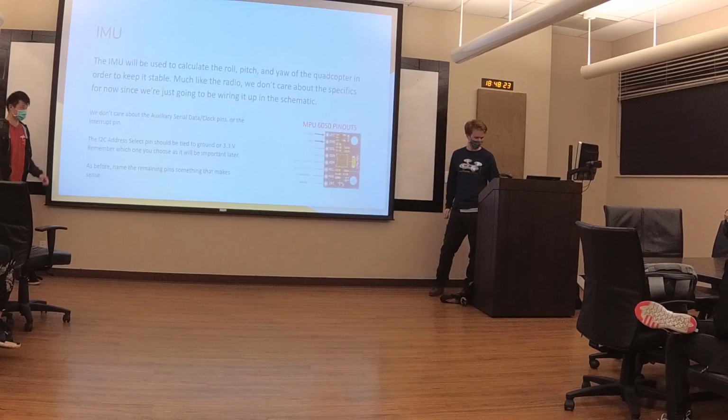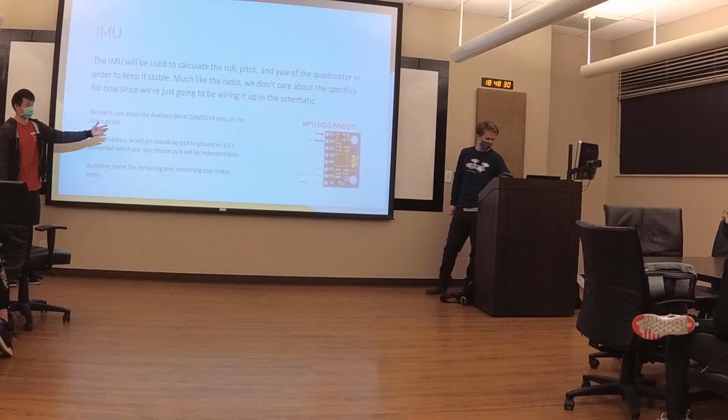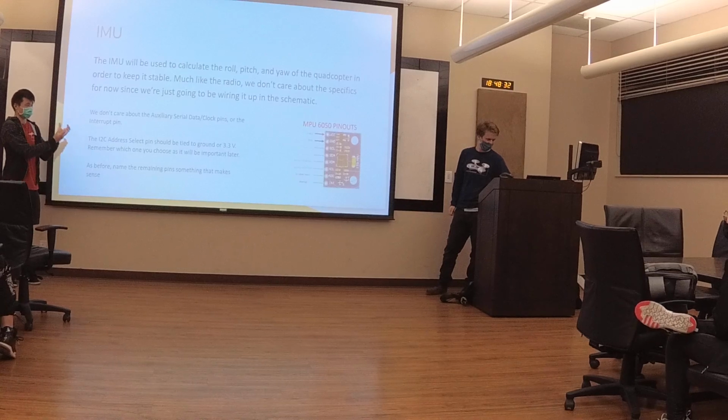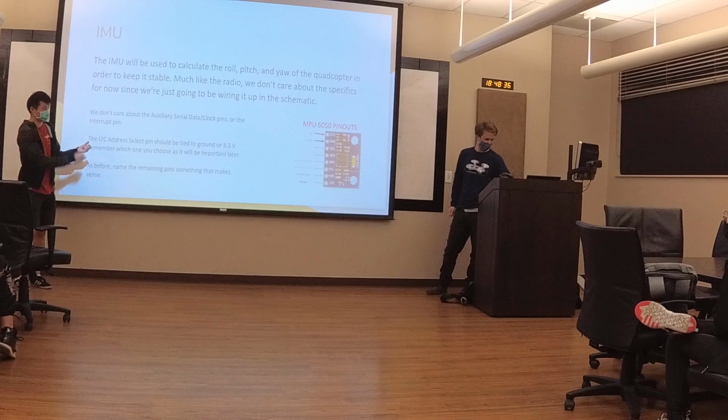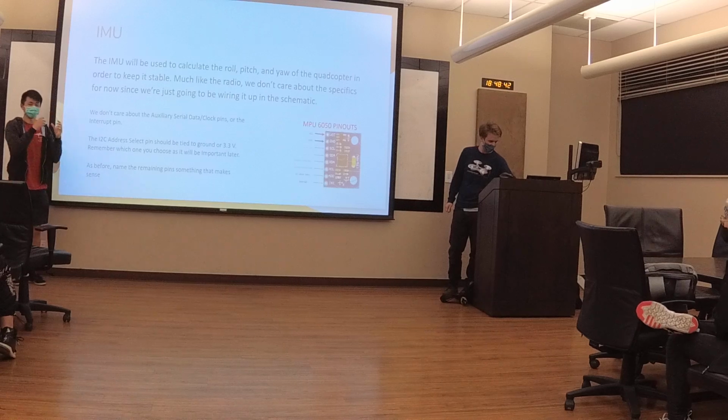As another heads up, something that I was confused about coming in was how these were going to be connected. These are breakout boards, meaning they have boards of their own, and we bought them. How we're going to connect them is with header pins. They're basically literal pins that will stick into these, and then we connect to our board like that. They're going to sit on top of it. So everything else is going to be soldered on.